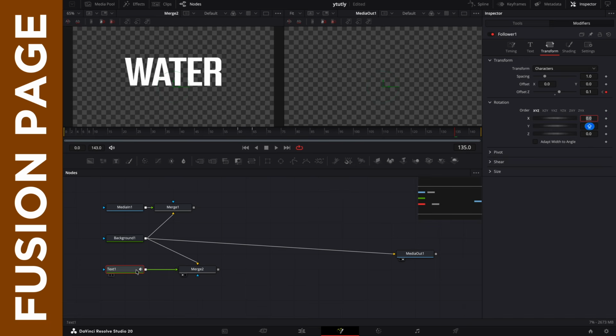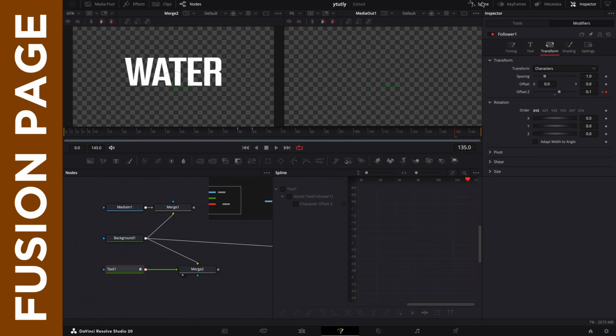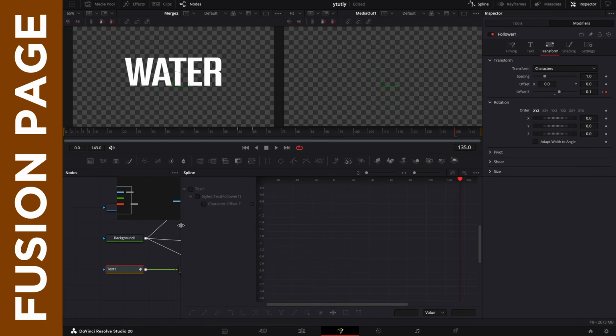Okay, so we go to the spline editor, open the spline editor up here. Let's expand it a little bit so we get to see more of it. Then we click on this character offset, click on zoom to fit up here, click on this icon here to select all the keyframes, then click on this to smoothen everything. So now the problem with this smooth is it's going all down here. So I'm just going to press F because I want it to flatten at the points like that. So I'm going to press F on the keyboard. Then close the spline editor.